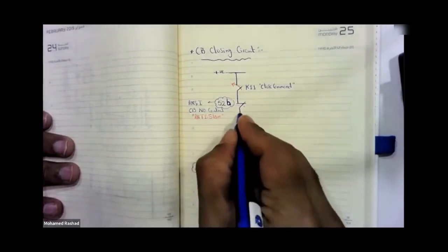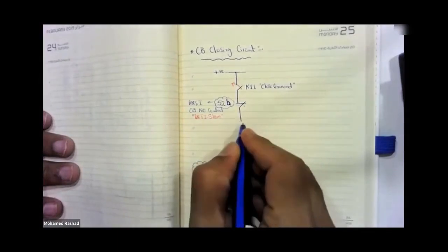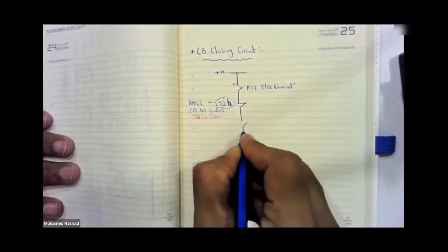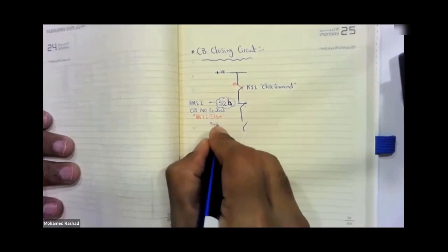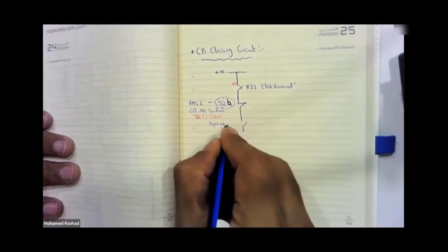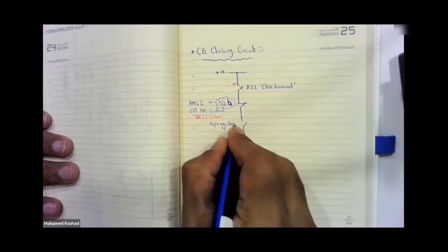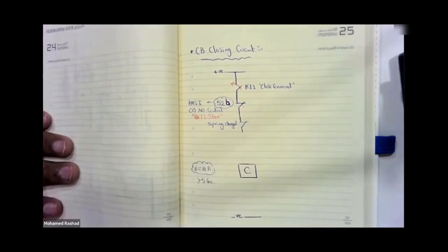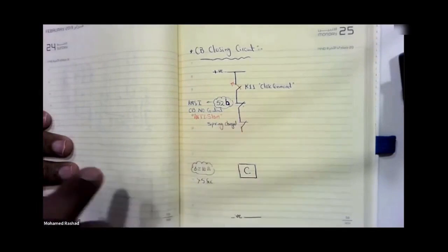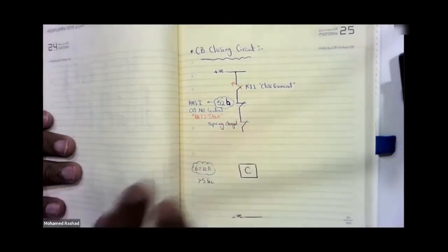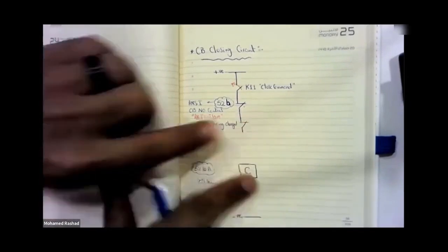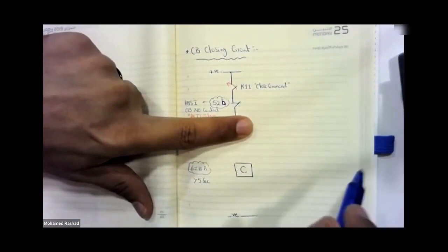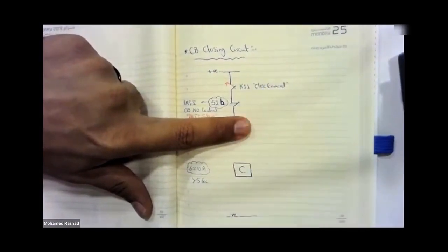Now, moving on, here we also find another contact from the spring, charged spring, exactly charged. Normally open or normally closed is taken here as normally closed, okay? If the spring is charged, you find this contact closed. If the spring is charged, what do you find? Open. So why is this not present now? If you give a close command and your spring is not charged, what will happen? The positive will go to the closing. Clear, the breaker is already open.